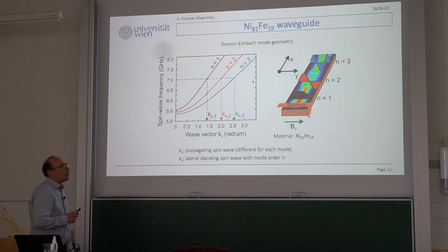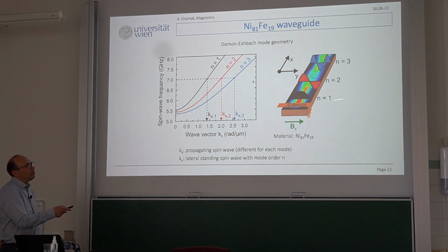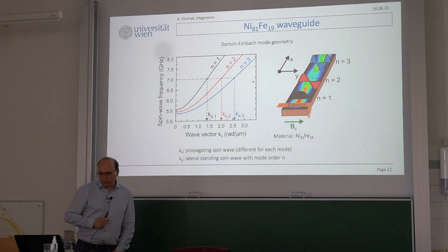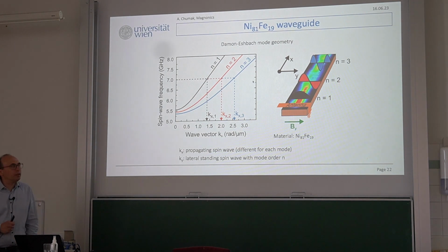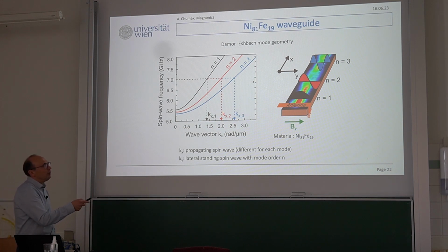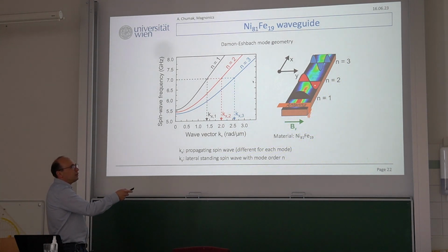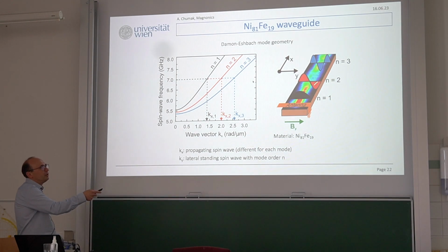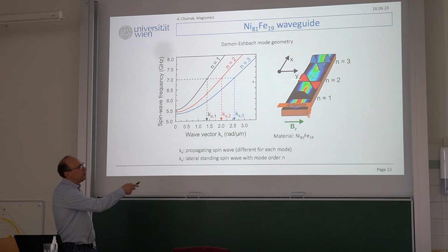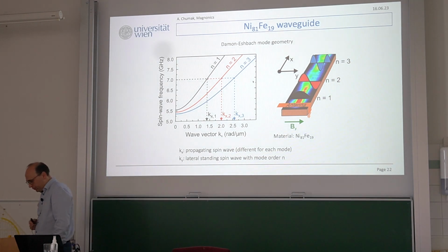And important is that usually when you use such a uniform antenna, you can excite only odd modes: first, third, fifth, and so on. Even modes like n equals 2 won't be measured and won't be excited, because the same antenna field, which is uniform across the whole waveguide, will be trying to excite this and this part of the wave, which are in antiphase. Therefore, you will be trying to excite this one and suppressing this one in one moment of time, and after half period, you're trying to excite this one and suppress this one. Therefore, usually with a uniform antenna, you cannot get the second mode.